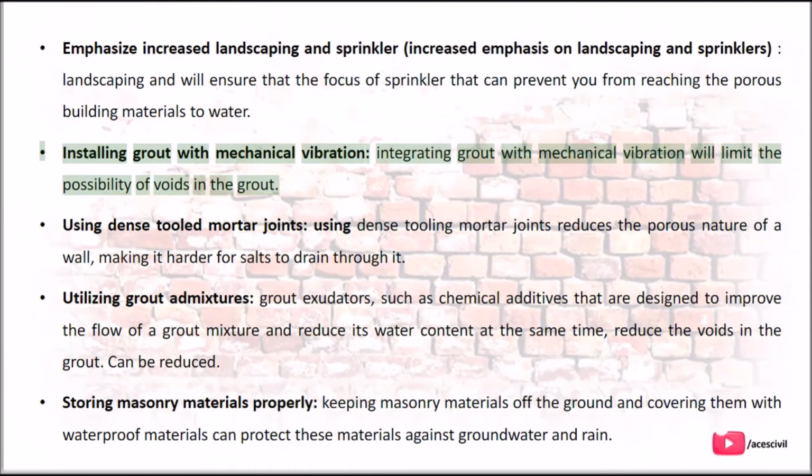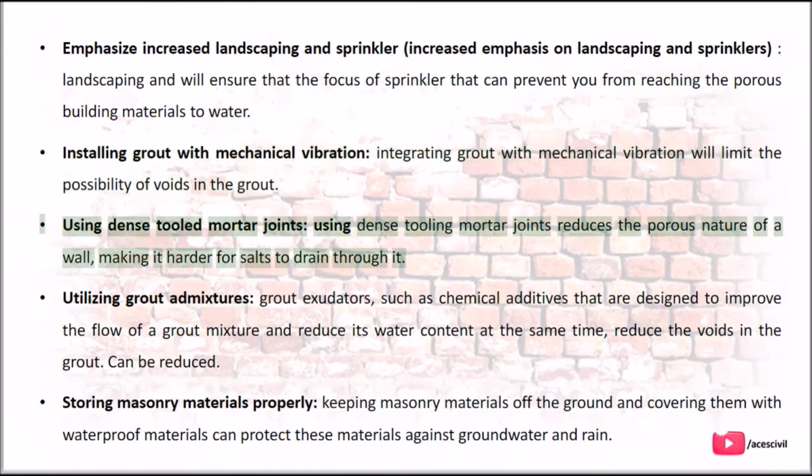Installing grout with mechanical vibration. Integrating grout with mechanical vibration will limit the possibility of voids in the grout. Using dense tooled mortar joints. Using dense tooled mortar joints reduces the porous nature of a wall, making it harder for salts to drain through it.